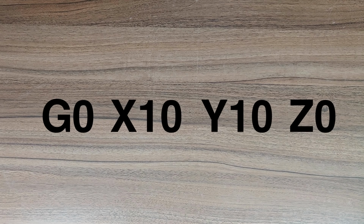To print any shape, there are 2 commands that form more than 90% of any G-code file. The first one of them being G0. Now this is a very simple command that tells the printer where to go at its maximum possible speed without extruding anything. We need to specify the X, Y and Z coordinates of where we want the nozzle to be, and the printer will simply move the nozzle to that particular point in space.